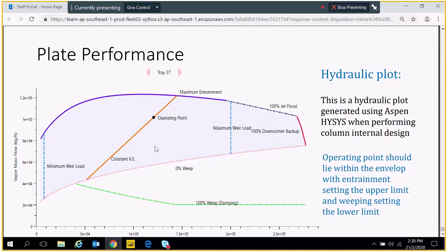So when you check the hydraulic plot, you check tray by tray. Now, by convention in Aspen, 0 is condenser, 1 is the top tray, because you're using the top-down numbering. If, let's say, the last tray is number 20, then 21 refers to the reboiler.